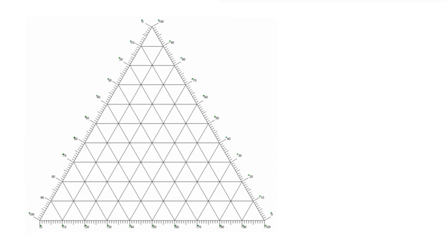I will call this vertex here the solvent vertex, S. The top vertex will be A, the solute concentration or weight fraction, and this bottom right vertex will be our carrier composition, C. The way this ternary diagram works is that the farther away on this equilateral triangle we are from some vertex, the less of whatever component we are looking at there will be.